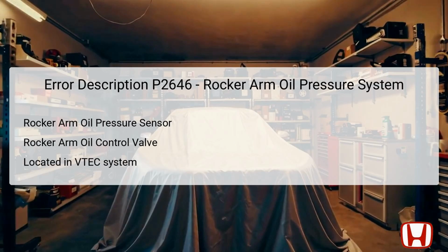The DTC P2646 specifically implicates two important components: the rocker arm oil pressure sensor and the rocker arm oil control valve, both of which are integral to the VTEC system in Honda engines.